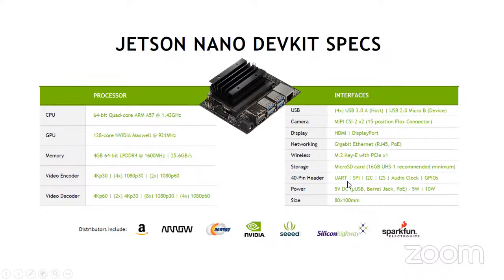If you take any type of ARM microcontroller or Pico, or other type of microcontroller, all those different types of controllers will have all these different communication peripherals. These are your serial communication, SPI, I2C serial communication, and I2S is audio communication using serial, and GPIO. GPIO means general purpose input output. We can connect basic, simple actuators and sensors using this GPIO connection.